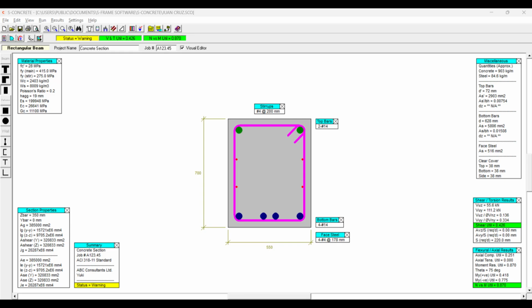During Module 1, the primary objective was to determine the internal forces acting on the beam. At this stage, the geometry of the beam and the applied loads were analyzed to determine the reactions, shear force, and bending moments throughout the beam. The calculations included determining the support reactions, constructing the shear force diagram, and constructing the bending moment diagram. These diagrams are very important because reinforced concrete beams are designed based on the maximum internal forces rather than